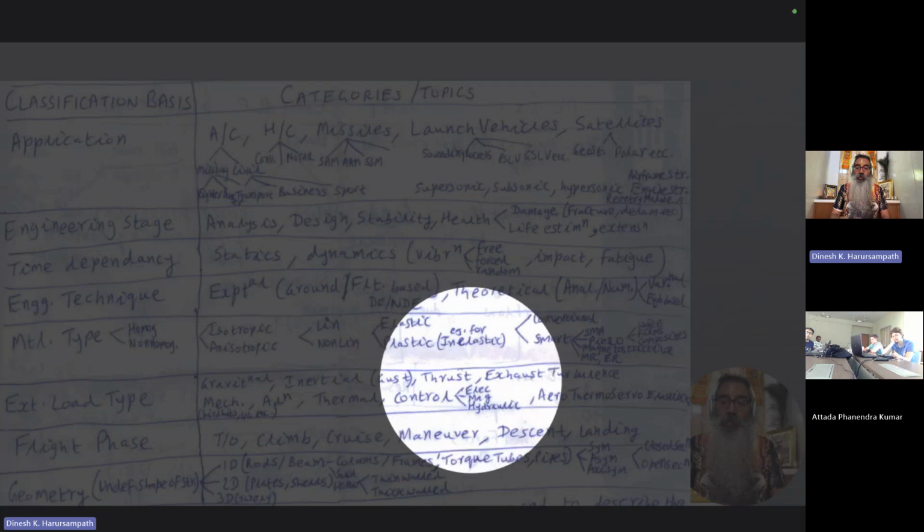So all of these come into the picture over there. Then there are the control loads, of course, coming from the aileron and the rudder and the elevator, or if it's an entire tail, the horizontal tail, which is rotating. And all of these are, of course, the flap deployment for takeoff and landing. All these kinds of spoilers, for that matter, to increase the drag at certain phases of the flight, especially on the ground, in order to ensure that certain on-ground maneuvers can be done.